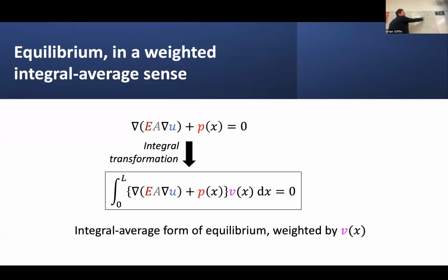But it's also kind of like a weighting function. It could be one of these Heaviside step type functions that assumes a discrete value, such that our interpretation is that we're effectively stating equilibrium over some finite chunk over which that particular function value is equal to 1, elsewhere equal to 0. Or we could describe it as a nice, smooth, continuous function that samples or tests the statement of equilibrium in a smoothed out way to identify the collection of points over which that function might be equal to something other than 0.